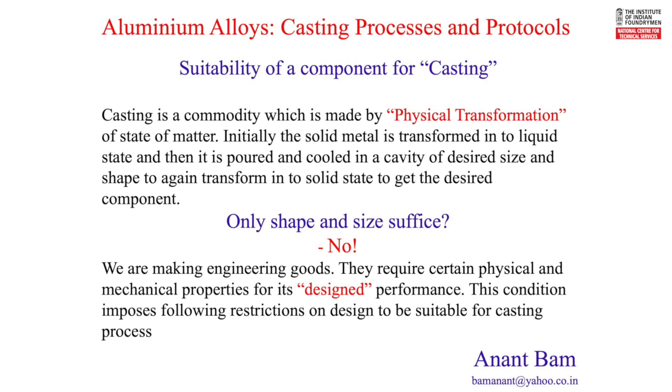Surface tension. Since the cavity of the mold is filled by a liquid, every liquid or every fluid for that matter has its own surface tension. And naturally, that surface tension prevents it from adhering to the adjacent surface. So any fine details, lettering, or any aesthetic feature is subject to the surface tension of the fluid or the metal. And hence, if surface tension increases, we cannot get a good piece.